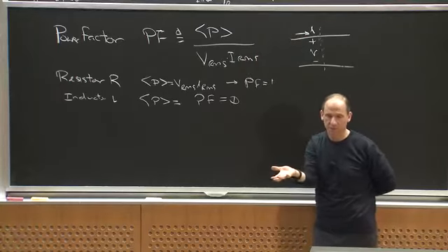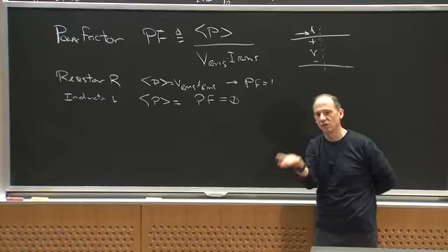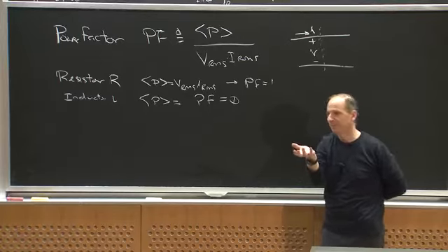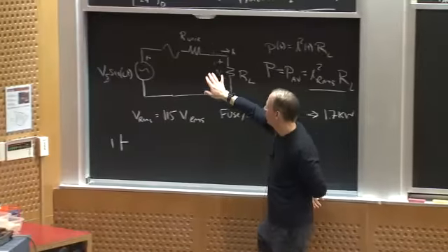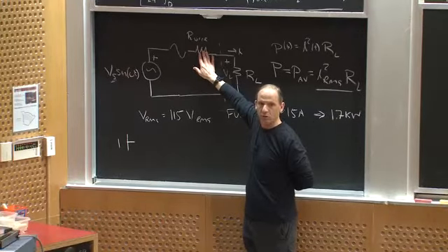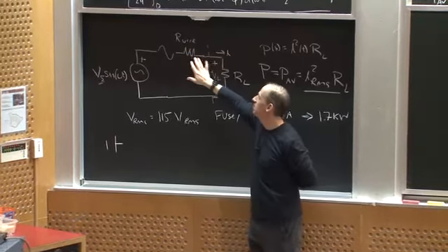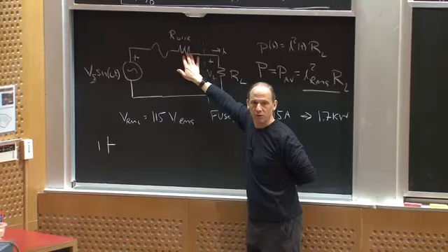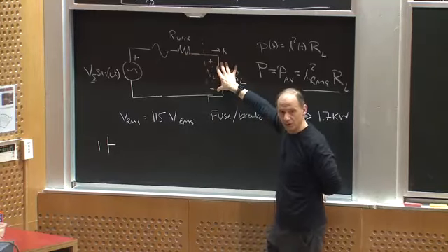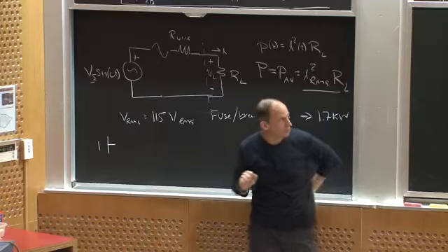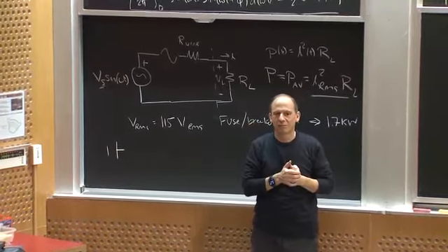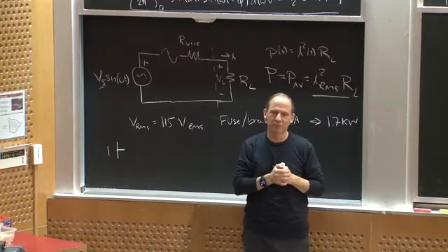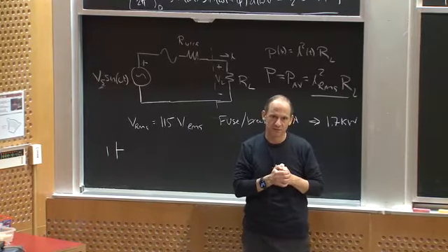Okay? And with a resistive load, a power factor of 1 means you're doing as little badness as you can, right? In other words, in order to draw energy in this example, yeah, I am dissipating something in the wire. There is some loss for the utility that they're paying for, right? But I'm minimizing the amount that's getting burned in the wiring resistance to transfer energy to my load. Whereas in the inductive case, I was doing the opposite thing. I was not taking any energy, but still causing them to have to pay for the loss in the transmission line. Does that make sense?